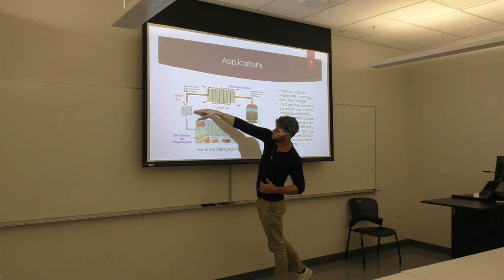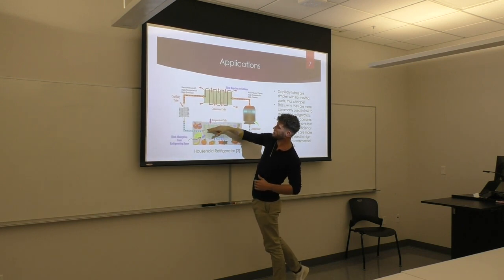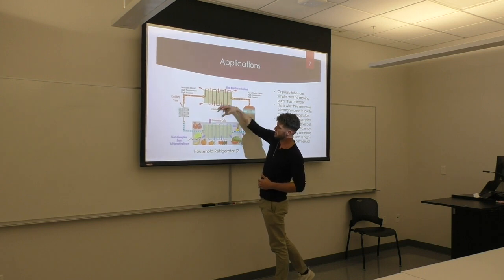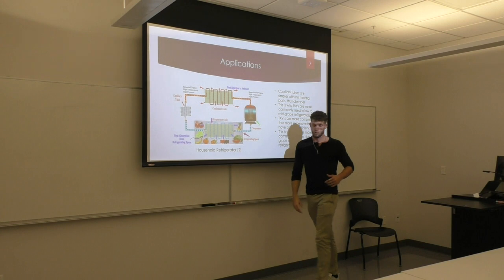And then it works through the capillary tubes, reduces pressure, and you got your evaporator, bringing it back to a superheated mixture. And it's doing that by pulling the energy in.